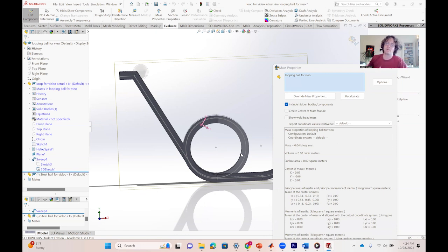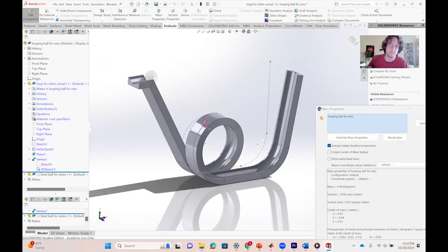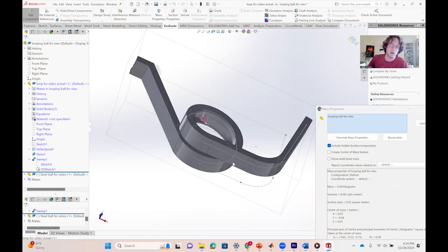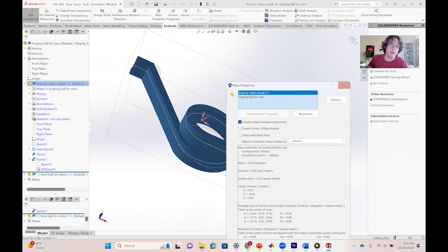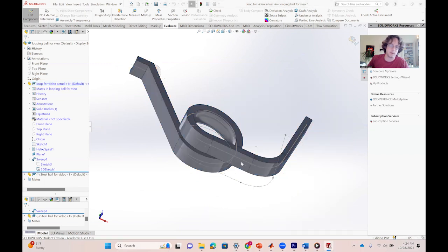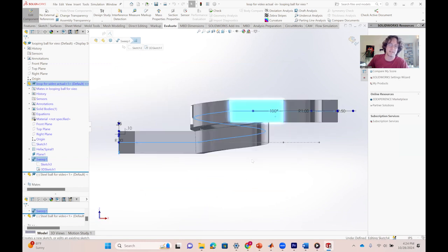Okay, so like if you create a table where the center of mass is not positioned in between the table legs, the table's going to tip over. So now what we can do to widen our table legs effectively, as we're editing this part, is go onto the bottom. Nope, don't want to do that. Want to get out of mass properties. Sorry. What we can do now is go onto the bottom surface there. You should have one if you made a horizontal line. So we're going to go onto the bottom surface there and sketch on it.